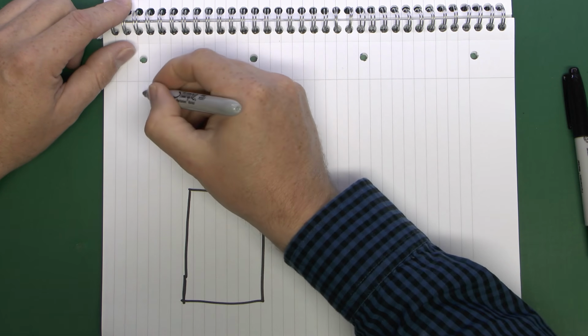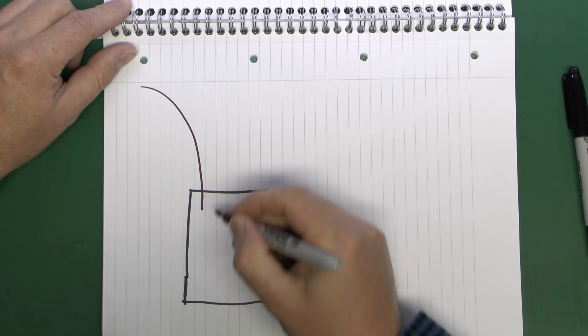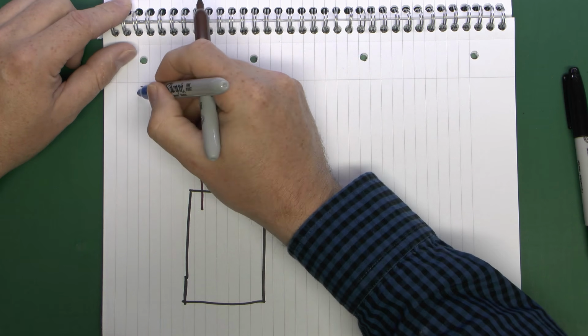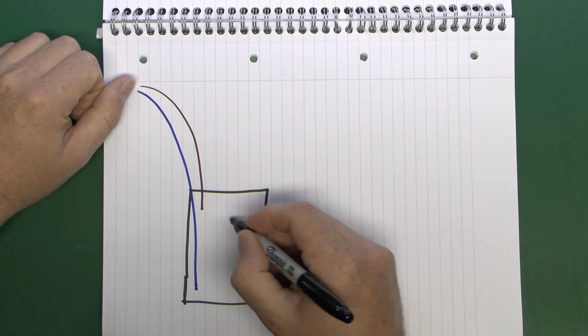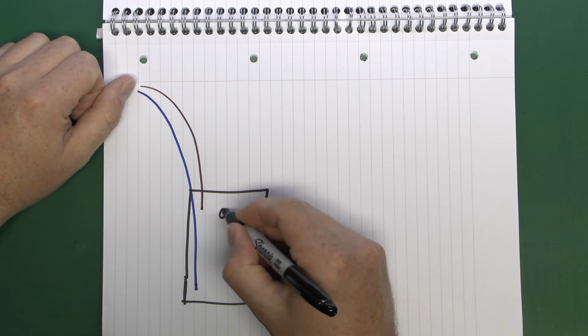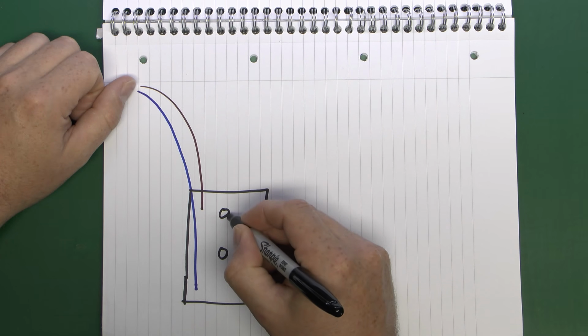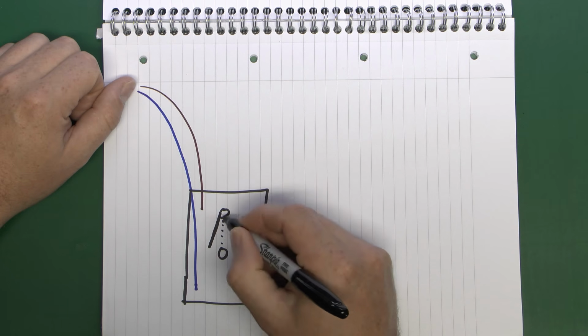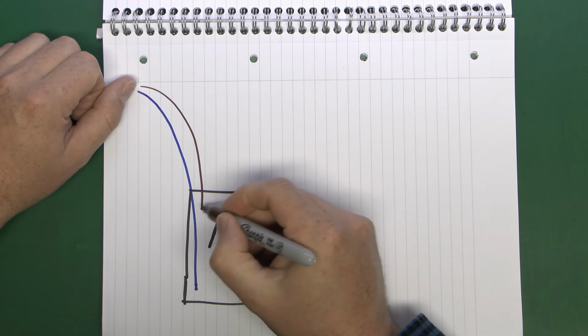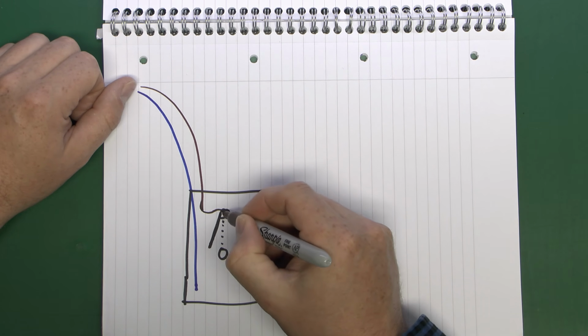So we're going to have our line coming in, and obviously the neutral as well. And inside here we're going to have the switch just as we did before, so there's our switch with the 2 terminals and the movable contact, of course, between the 2 there, which can obviously connect the 2 together. So the line coming in goes straight onto the switch terminal here,